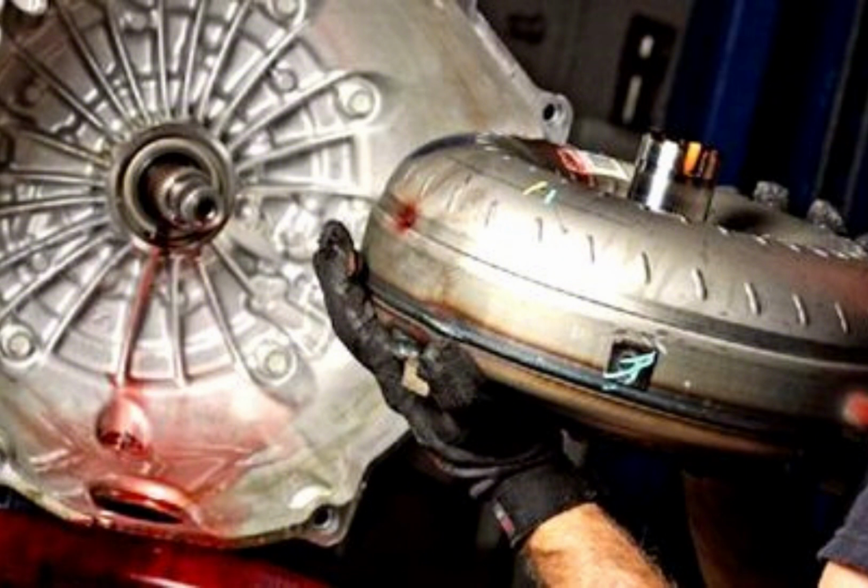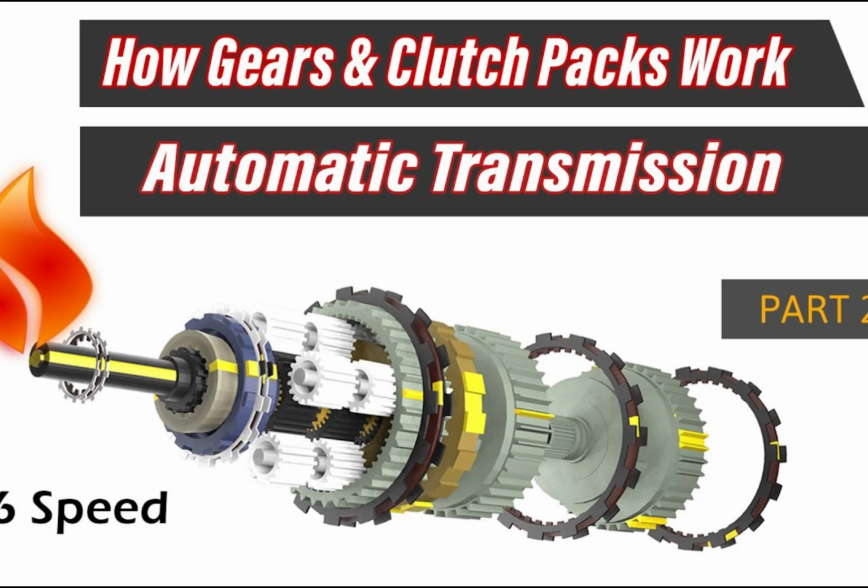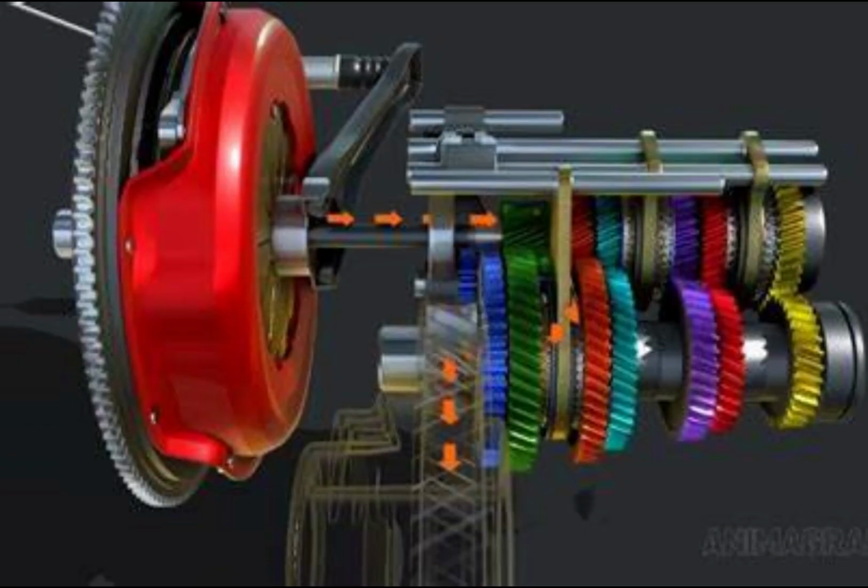Discover how automatic transmissions work and learn the step-by-step process of repairing a B13 automatic transmission. This video explains the essential components, including the valve body, clutch packs, torque converter, and planetary gears, and highlights their roles during driving. Follow detailed instructions on removing, disassembling, and reassembling the transmission while identifying critical parts to handle with care. We also cover tools needed for the job and troubleshooting common transmission issues like slipping gears and fluid leaks.